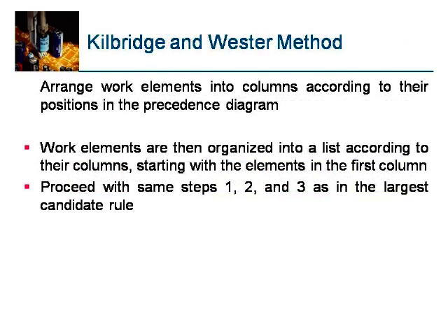That's how the physical layout of workstations and assignment of work elements to the stations is done according to the largest candidate rule. If you see here, the elemental time at each station is supposed to be equal to 1, but it is not, because of the total variations. The total time for this is different, for this is different, for this is different. This is unavoidable. So if the total work content time is 4 minutes, here there is going to be a delay because the total number of stations is more here.